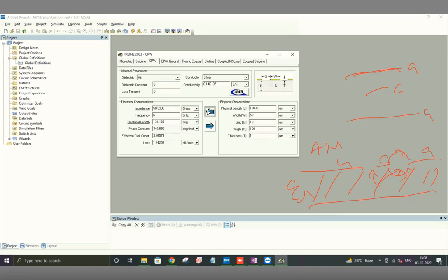One of the really nice things about the CPW is that you can make very large CPWs and very small CPWs because it's the ratio of the width and the gap which determines the characteristic impedance. And that is very convenient because you can have very large transmission line CPWs which can interface with big connectors where you're bringing the signals in.